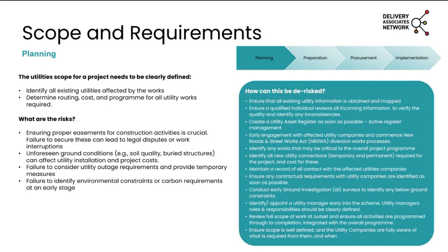Undertaking ground investigation surveys. There are different levels of survey that you will undertake across the route, and it's not realistic to undertake boreholes every 10 meters. So it'll be targeted in certain areas where there's normally a lot of utilities or there is a significantly higher risk. But the sooner you get that information from those surveys, the sooner that can start informing the design.